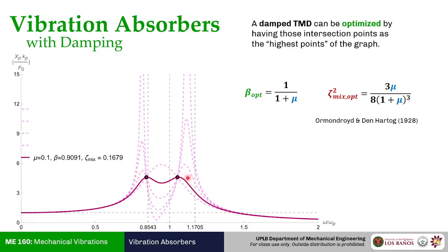And let's say, okay, so what is the implication of this? So if my initial threshold was, I just want magnitude less than 10, if you see here, it's possible to actually have an entirely safe frequency range. So if initially we said, I want a primary magnitude of 10 or less, and I will declare that safe for my system, if you look here, all of your range is essentially safe. And that is the beauty of the optimized tuned mass damper.